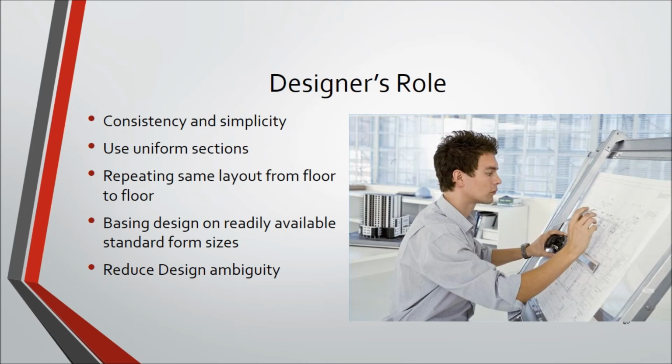The role of the designer is very important. He must focus his designs on being consistent and simple. He should focus on using uniform sections, and if possible repeat same layout from floor to floor. He must try to base his designs on readily available form sizes. It is at the design phase that maximum savings can be secured.